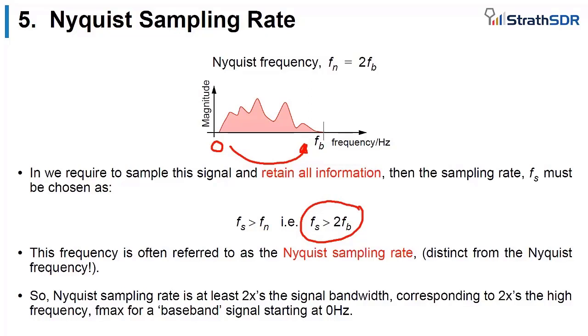And for more detailed reviews of the capability of the RFSOC, that's quite an important point, because many of the radio frequency signals we will look at are in fact band limited, like a 40 megahertz mobile radio channel or a 10 megahertz 4G channel. So that's something we could focus on when you do your actual real designs and implementations.